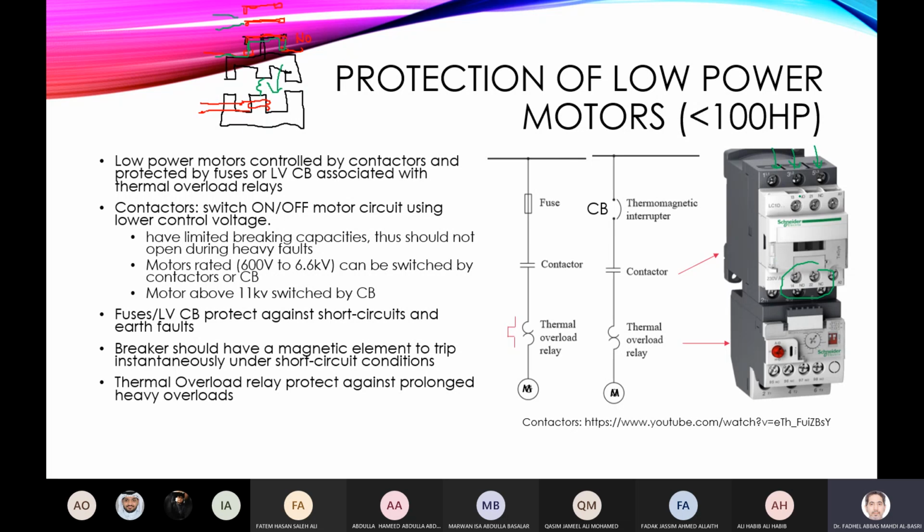The problem with contactors is that they have limited breaking capacities. You cannot break any fault currents like circuit breakers, which are also designed with limited breaking capacities. The contactor is normally designed to break up to 10 times its rated current.